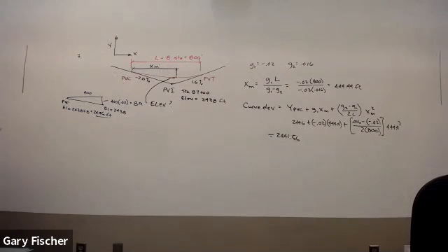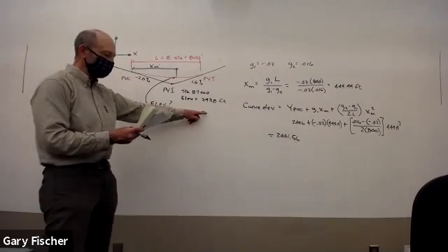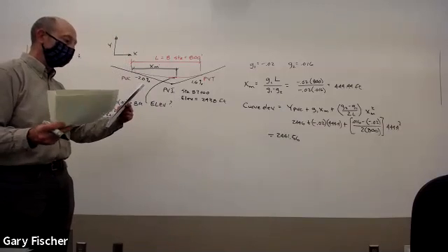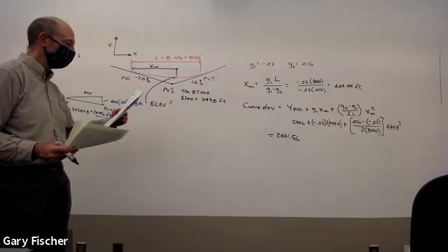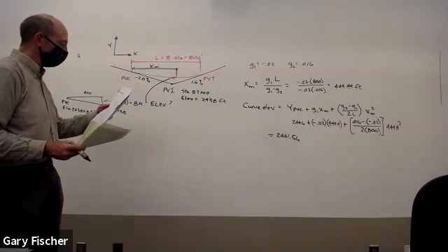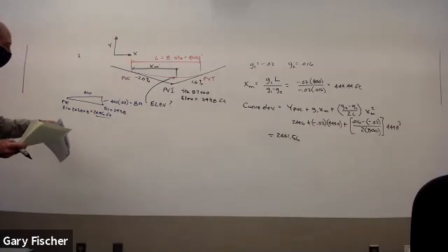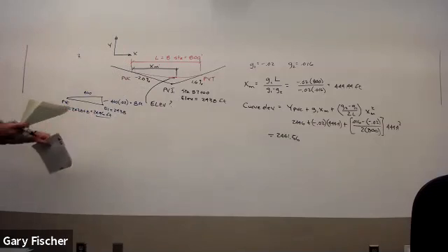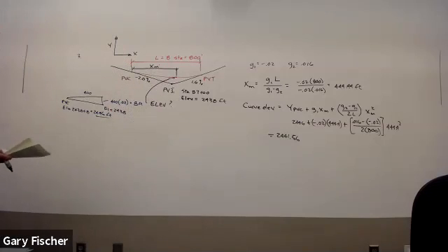A better way you can try to do that: we know it's not going to be less than 2438, so you can eliminate the first two choices. So it's somewhere between there. It's not going to be higher than 2446, the PVC elevation, either. So you don't have to go as far as I did. You could stop and figure that one out. Okay, that's all I got.